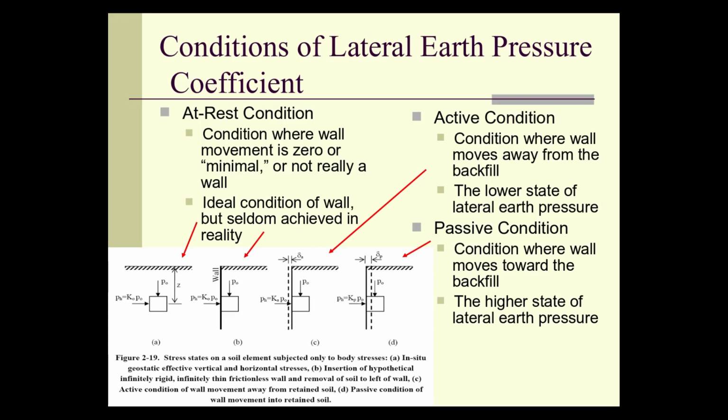On the other hand, in some cases, and active cases, by the way, are what we most normally think about when we think about a retaining wall holding back soil. Most of the time, when the soil is pressed down, the lateral earth pressure attempts to push the wall, and the wall tends to be pushed away from it, or runs away, so to speak, from it. And those are active pressures.